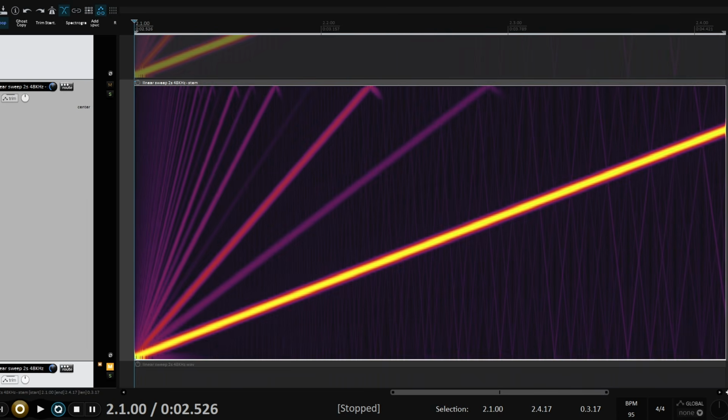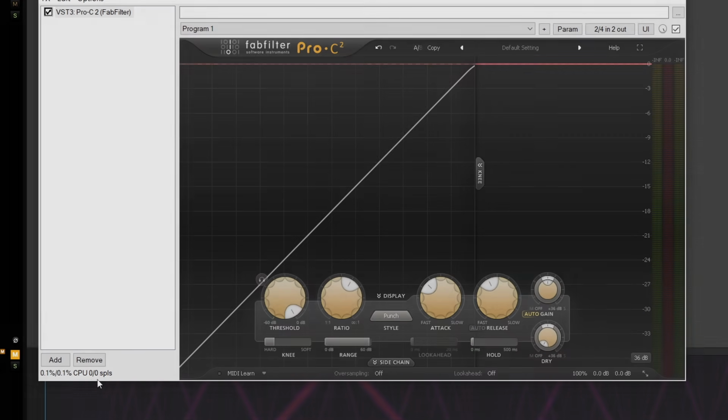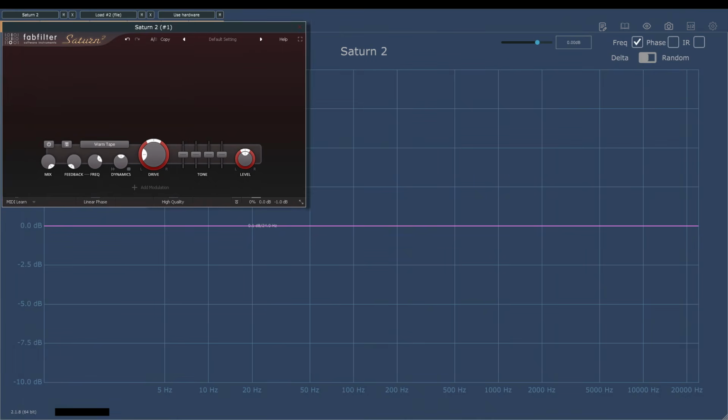The next question might be, are these up and down sampling filters linear phase or minimum phase? Actually, you get a big hint from the plugin's latency. If it increases significantly when oversampling is enabled, that suggests linear phase. A more definitive test, however, would be to measure the phase response in Plugin Doctor.